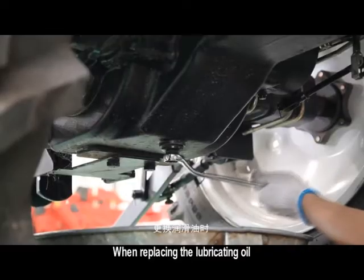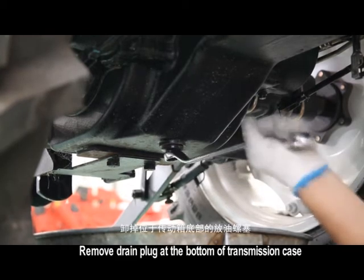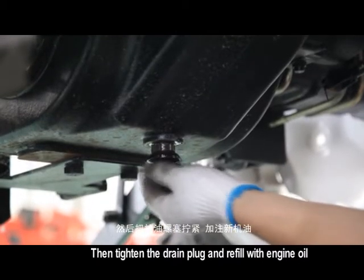When replacing the lubricating oil, remove drain plug at the bottom of transmission case. Empty dirty oil. Then tighten the drain plug and refill with engine oil.